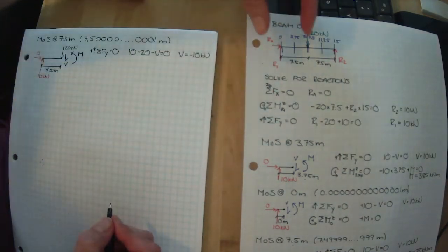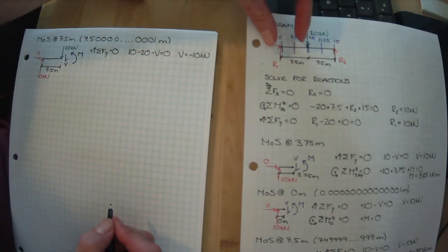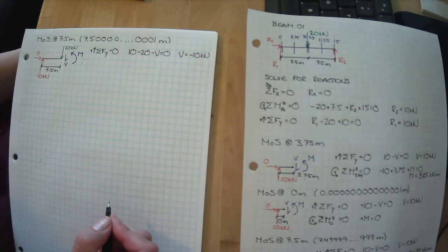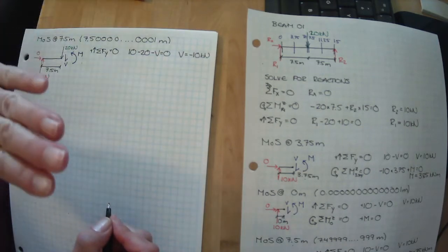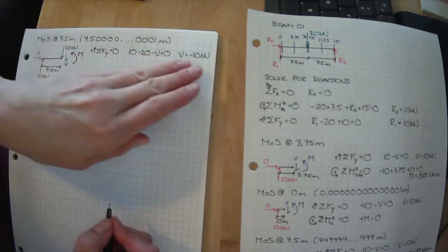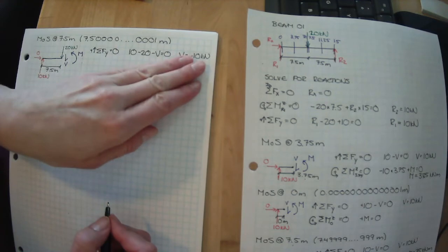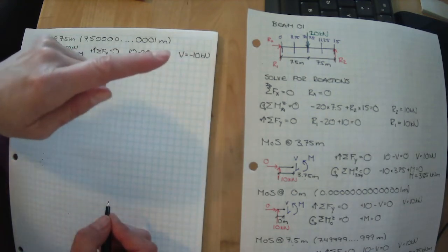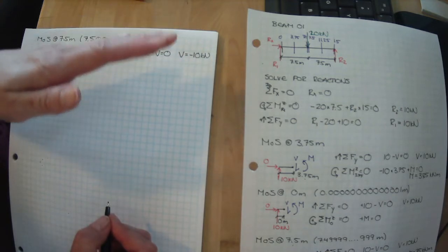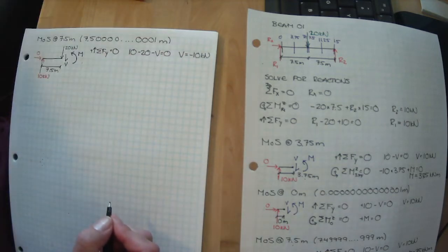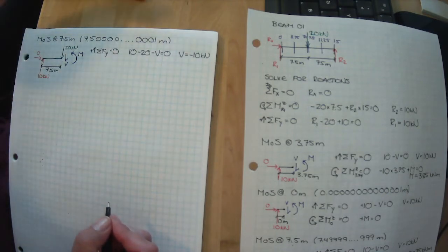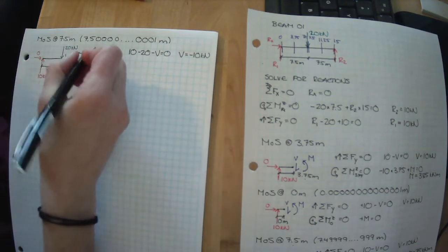Okay, everywhere on this side of the beam, we had plus 10 kilonewtons. And now something's happened and we've gone to minus 10 kilonewtons. All right, just hold on to that knowledge for now. We'll come back and we'll talk about that. But we've done the calculation and we've seen what it does here. I think what might be handy is if in a little bit we draw what's happening. And so we're going to start talking about not just drawing axial force diagrams, we're going to introduce drawing shear force diagrams as well, because that might help us understand this.